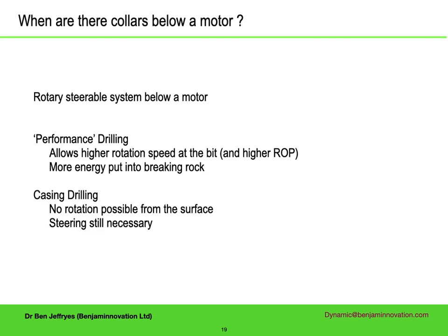The other case is casing drilling. Normally, steel casing is run into hole after it has been drilled. There are different methods for doing both jobs at the same time, one of which is to drill with a BHA below a motor, which is mounted in the casing. After drilling, the BHA is removed using wireline. The BHA has to include underreamers to allow the casing down, and any steering, surveying or other tools, so it can be quite long.